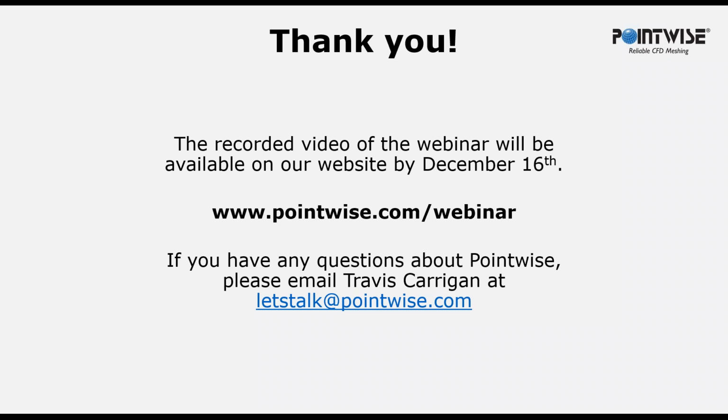Okay, so let's go back to our questions. All right, can two sources intersect? You can have as many sources as you want in your mesh. They can be independent of each other in space, or they can overlap. And when they overlap, Pointwise will use some algorithms to determine which areas of which source have greater influence over the volume mesh if they are significantly different. So yes, you can have overlapping and intersecting sources.